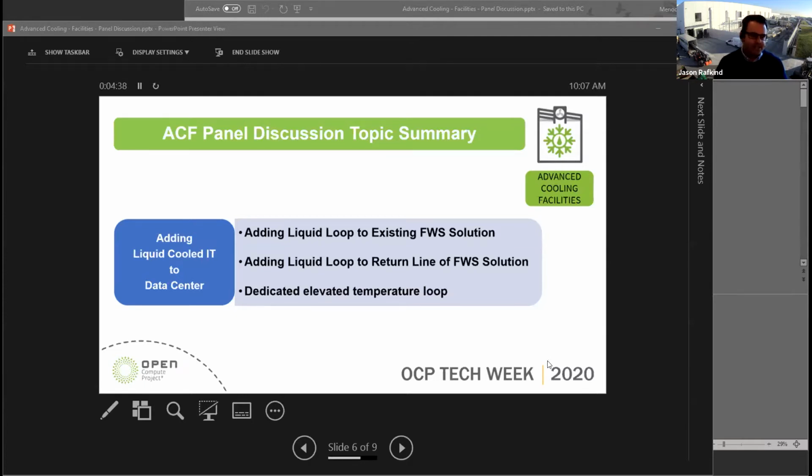So we started thinking about how to best solve those. Our current basis of design is on a slab floor. We do have 14 feet of clear height between the floor and the ceiling. So how can we make that work? Obviously one idea is to bring the chilled water into the data center floor onto the slab, connect to a CDU, and then distribute overhead.